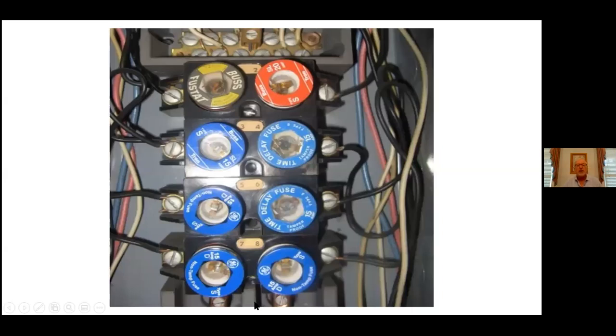So here we're looking at a very clean electrical panel with our fuses. One of the interesting things is, why do we take off the cover? And we'll cover that in just a minute. But in here, you can see that in this particular case, both here and here, we have 2 wires coming into each fuse. And that is an absolute overload immediately. That should not be happening.